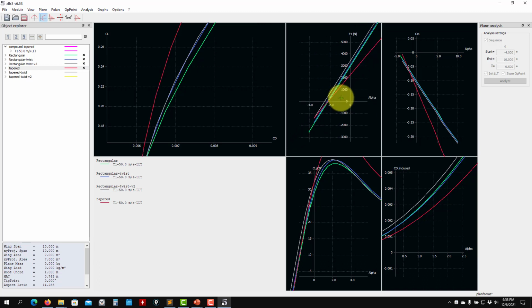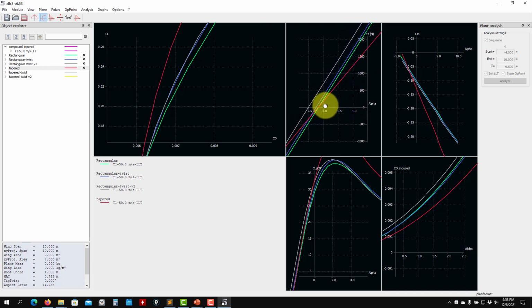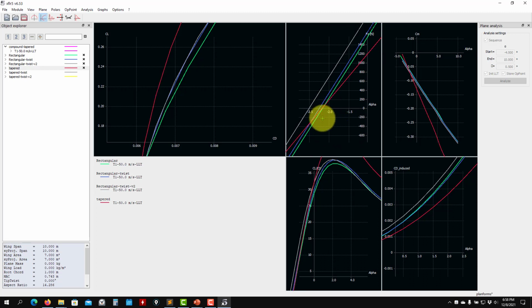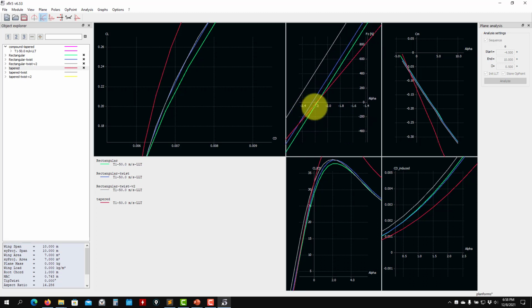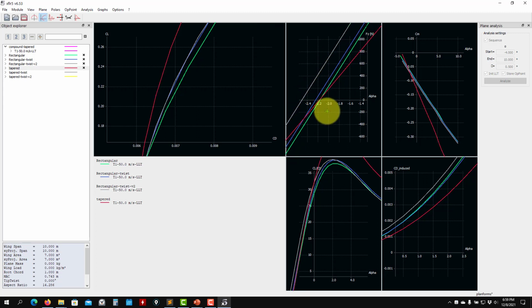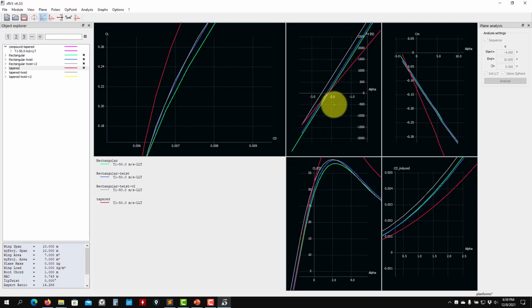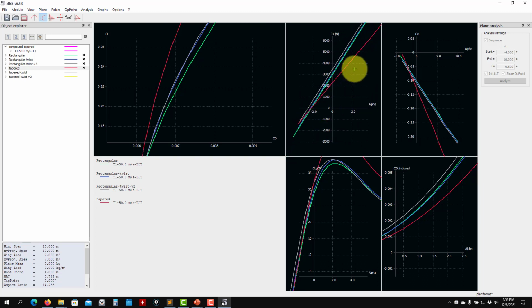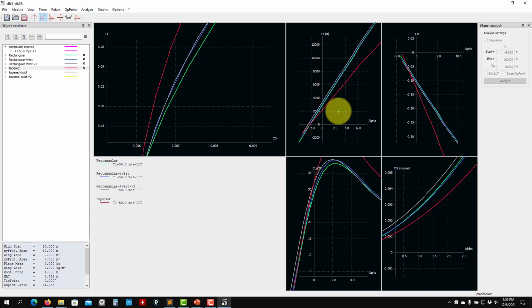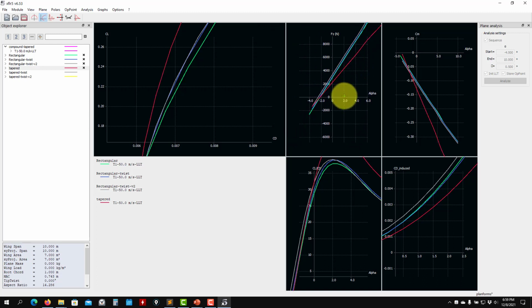One thing that I also want to point out here, that I mentioned, is that the wing tends to inherit all the properties of the airfoil. So if you check your 2D airfoil, you will see that the angle of attack for zero lift is something about here. See that they are all centered here. This one is a little bit different. Remember that we changed the twist and everything, so you have that shifting. But clearly you see here that it's inheriting a lot of information. But see that taper also has an effect that will reduce your lift curve slope. Since that might be evident, you have different surfaces. That effect you will see here.